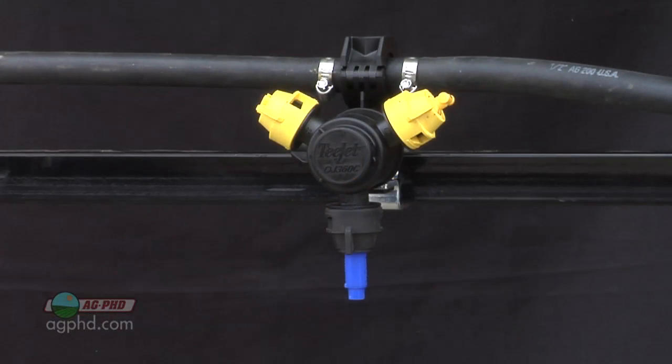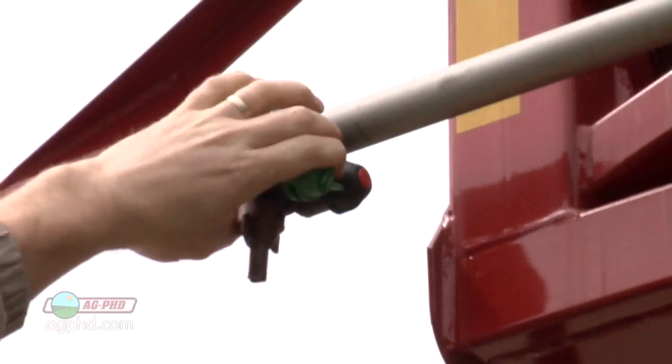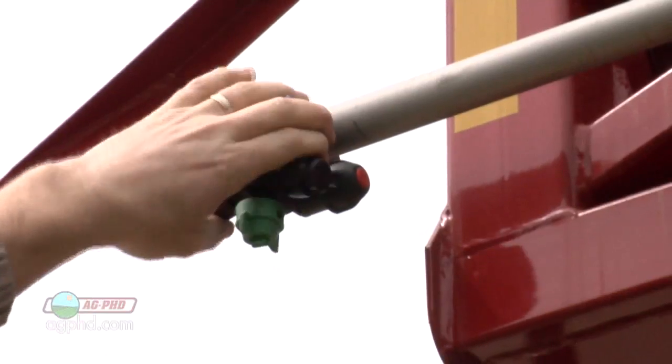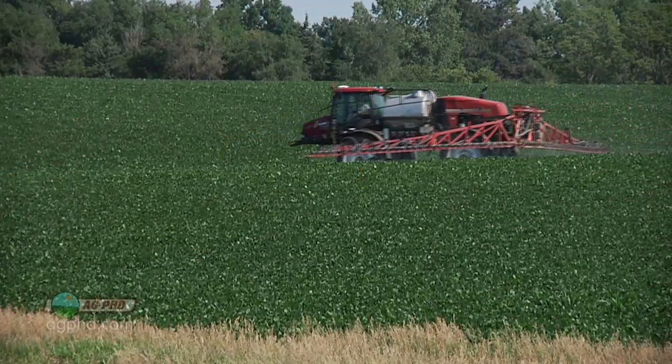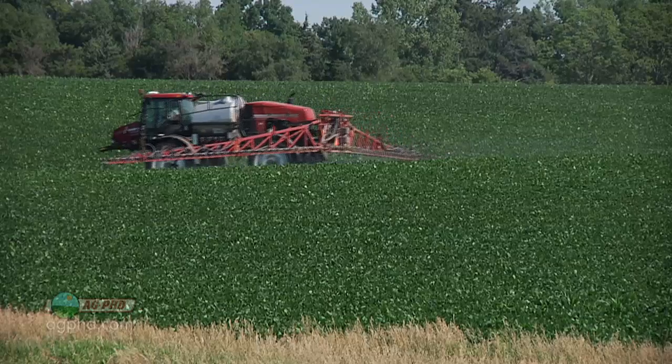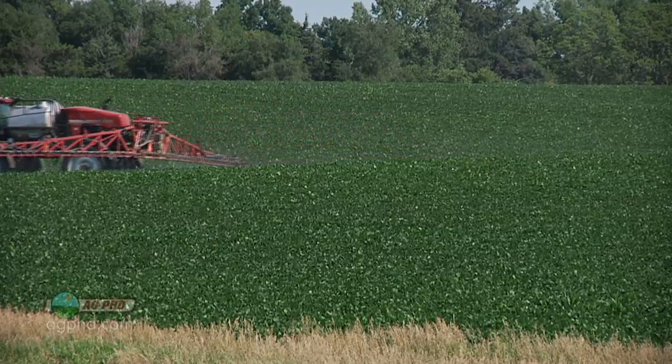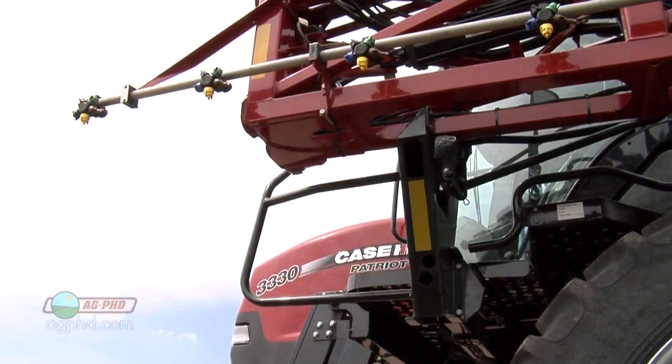You may be out spraying like right now and it's still, there's no wind at all. Yep. And then all of a sudden a gust comes up and here comes a front passing through, and now we've got 10-mile-an-hour winds. Well, if you've got a triple nozzle body or maybe a 5-way nozzle body, you can just walk out behind your sprayer, click, click, click, and in a minute or less, you've switched all your nozzles from a drift control type nozzle over to a flat fan nozzle or whatever you want to switch to. You can do it really quickly and easily right in the middle of a field.